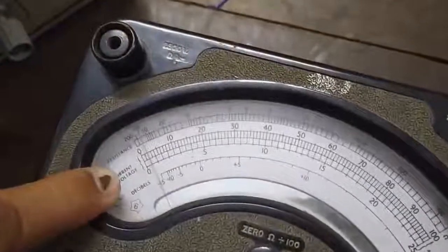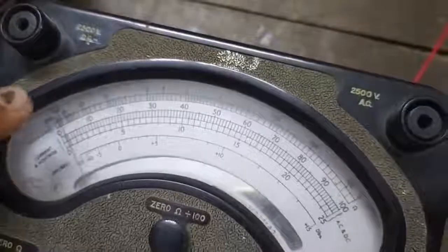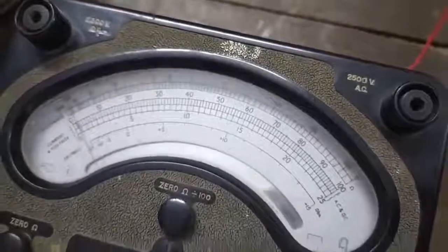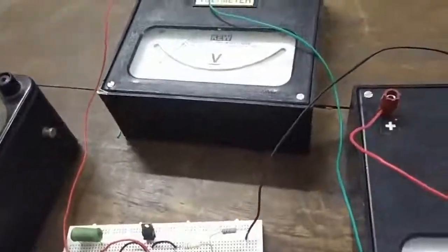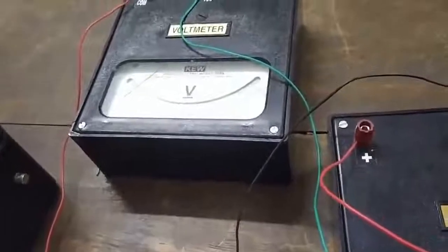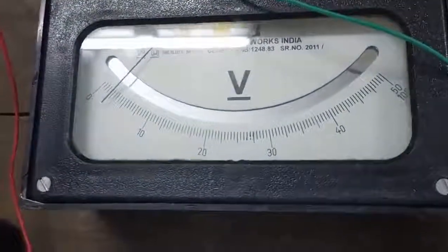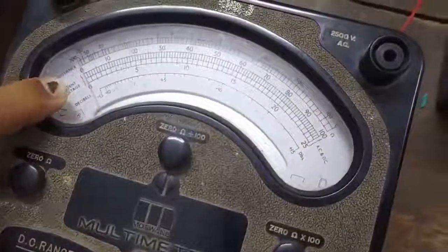So applied voltage is 20 volt. Now you can see here the anode current, now it is in the range of 0 to 10 milliamps. It is less than 1 milliamp. It is around 0.3 milliamps. Now first we apply the voltage in 5 volt steps, and for each step we will take the reading. Say now I applied the 5 volt. At 5 volt the current is 0.1 milliamps here, very small current.